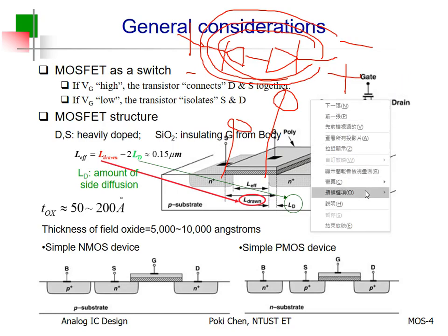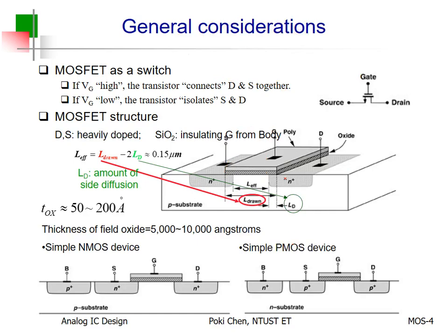So it means what? If you would like to fabricate PMOS, the source and the drain need to be highly doped as P+. But P+, P minus, P+. What does it mean? No parasitic diode from the very beginning, right?